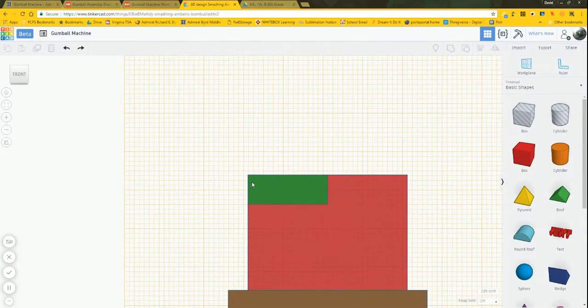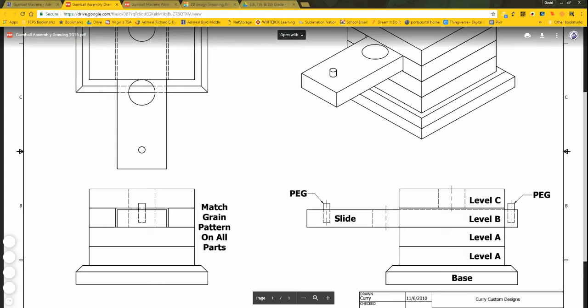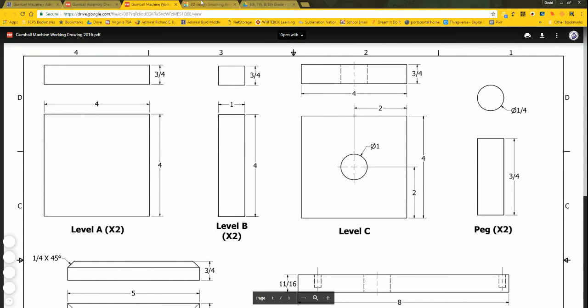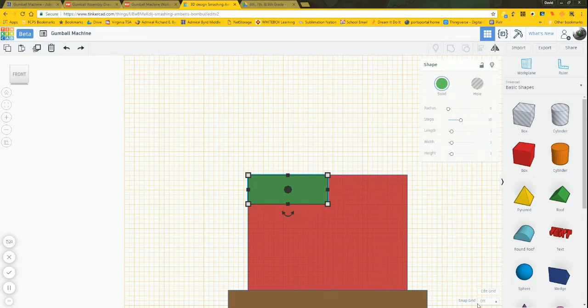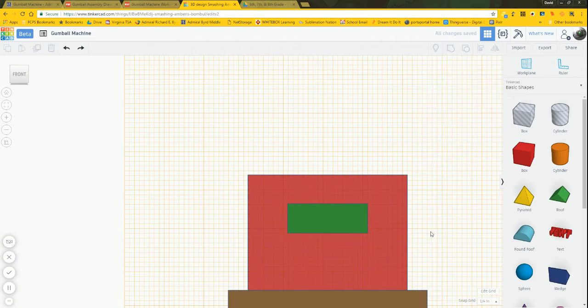So, since I need to be 3/4 of an inch down and basically 1 inch over, and again, the reason for that, this is 1 inch. This is going to be a hole, so 1 inch over, 3/4 down. I'm going to go ahead and set my snap grid to 1/4. With that, of course, 4/4 would be 1 inch. So I'm going to go to the right 1, 2, 3, 4/4, and I need 3/4 down. So 1, 2, 3 down. There's my placement for this part.